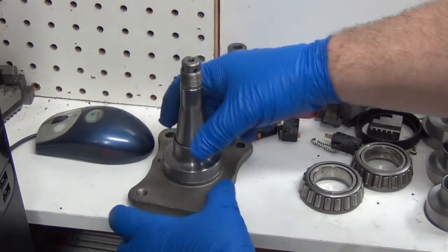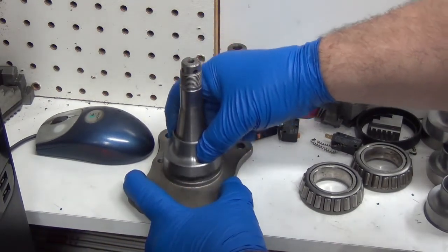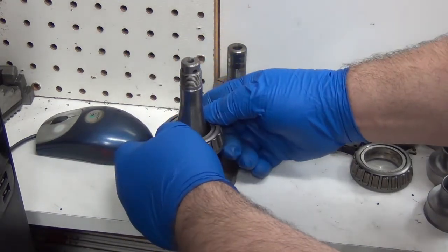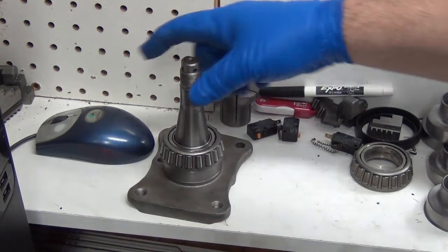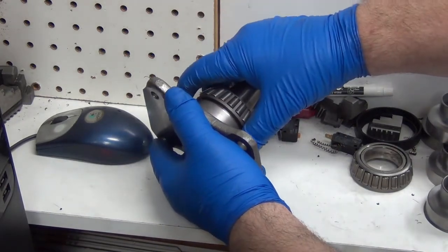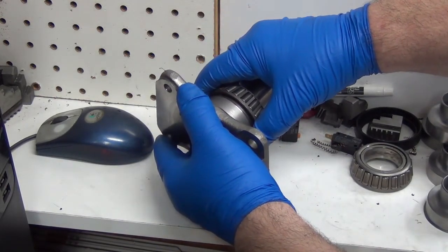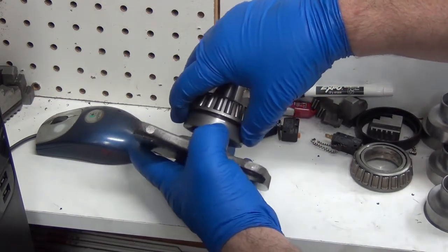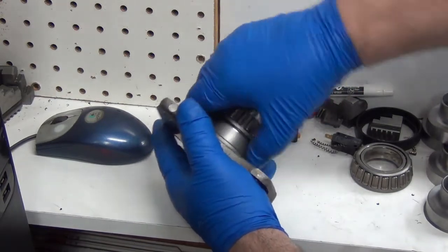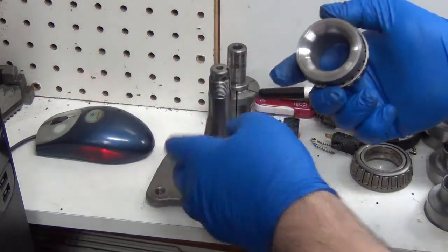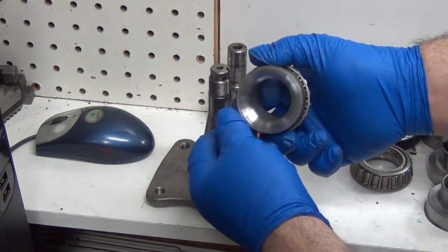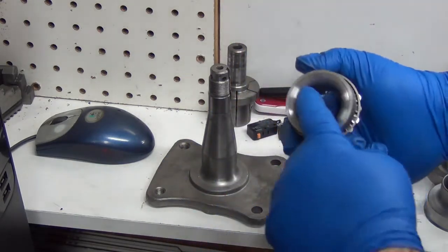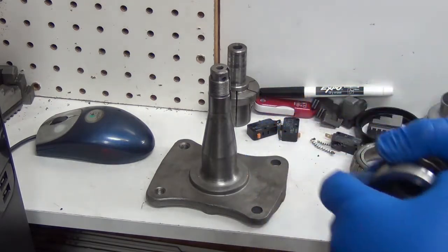Now, this one's a little loose, that's why it's a test part. But nice. All right, we'll do another one because I want to make sure we don't touch anywhere. So after I get the next one done and it matches more flush here, I'll put some Sharpie on here to dye-check it basically, and we'll find out where it touches and rubs. Then that'll be good to go.